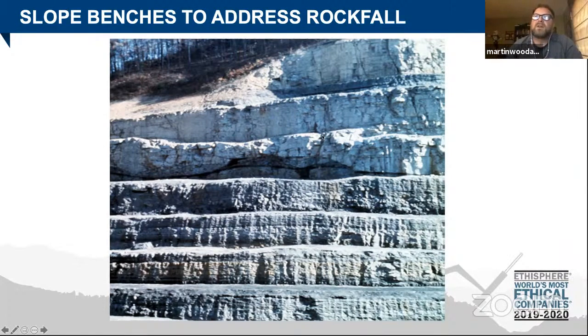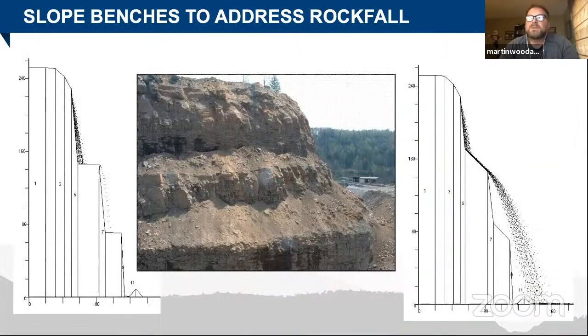And you start to take a look at rockfall. If you look at the one that's up in here and it falls onto that bench, it actually does a really good job of catching a lot of the rockfall. And benches can be used if you have the right geology to put these types of things in. The one word of caution, especially if you're not in a mining environment where you have machinery out there readily, is that sometimes your benches do get filled up and they do degrade.